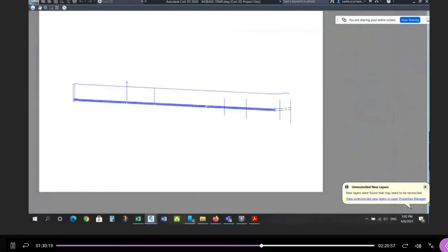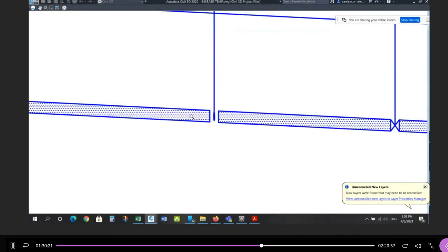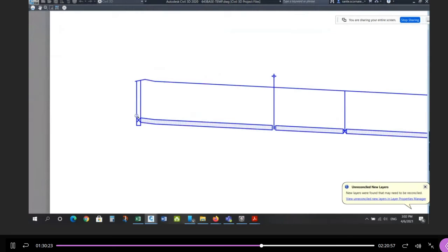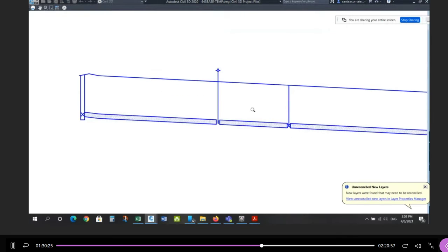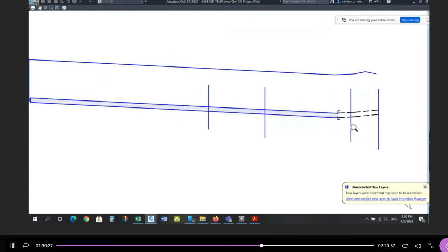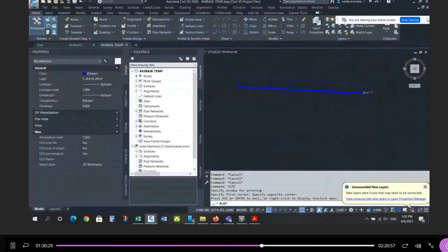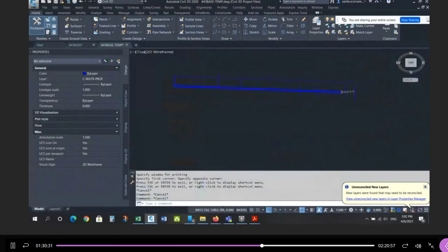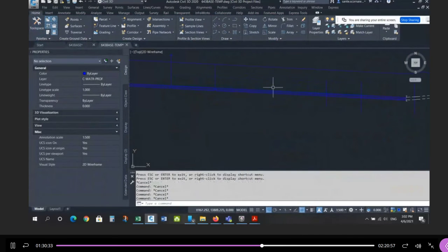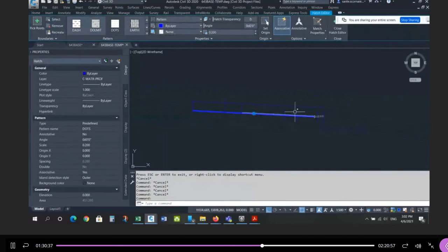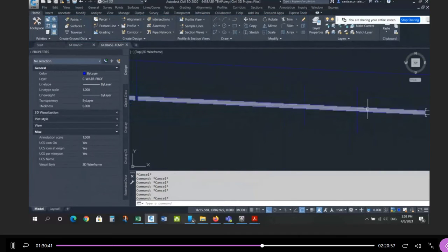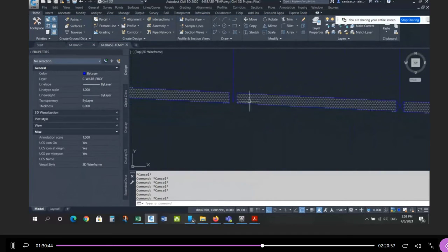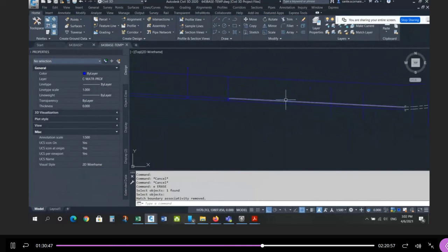It starts to look a lot like the stuff that we saw. Valve chamber, hydrant, valve box, and so on. Again, it's your AutoCAD skills that are going to take you through this process. Don't do any hatching until you draw all the hardware, otherwise you have to break this again. There's going to be a gap here and a gap here, just like these two. So don't hatch until that. Hatching is the last thing you do.